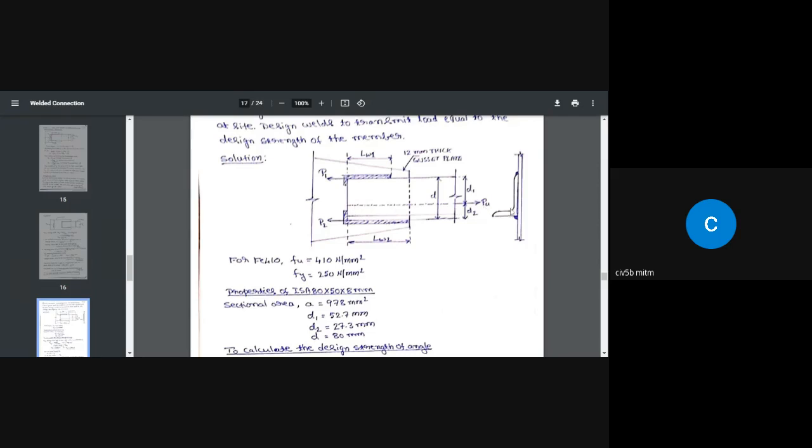When you look from this side, this is what you see, and if you extend this neutral plane to the cross section, it is the neutral axis. This is D2, from the bottom of the shorter edge to this line, the neutral axis depth, and from the top, D1 is the neutral axis depth.